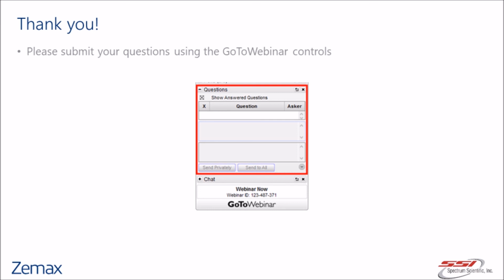And then tolerancing the surface irregularity is a little bit trickier. You can use the TPAR commands to tolerance the coefficients directly. When you do that, you do need to go back into, for example, your Monte Carlo files and check what the RMS deviation was for the part, because in that case, what you put in is the tolerance that you can allow for each coefficient.